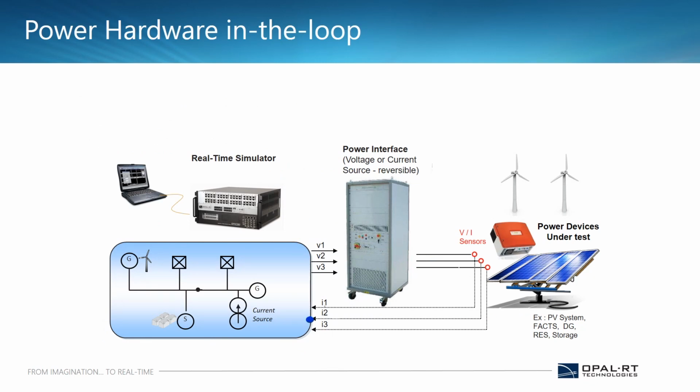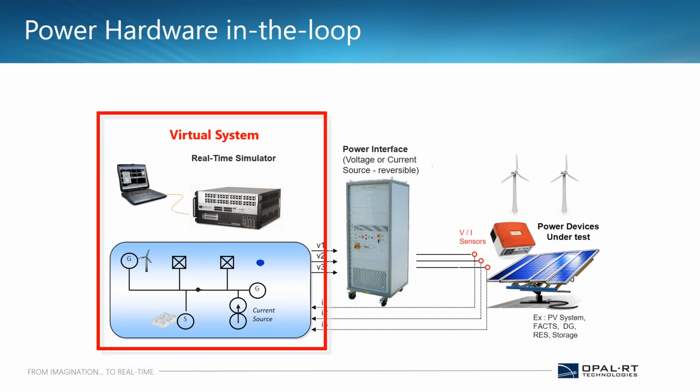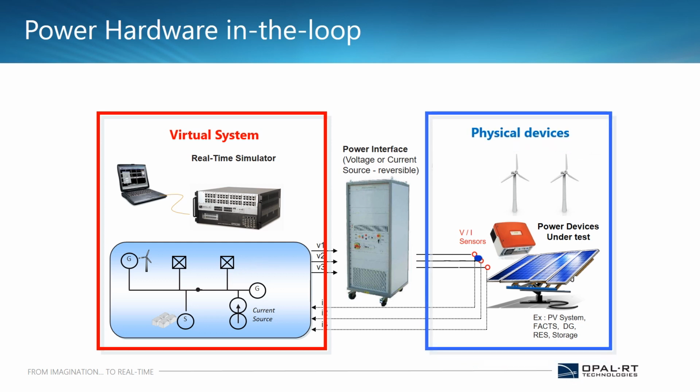So what we will do, we will take the voltage and current results from the real-time model which is running on the real-time platform. We'll send it to a relay, the hardware relay. Then the hardware relay will give a trip signal based on the voltage and current commands that it has received from the real-time simulator. Then this trip signal will go back to the MATLAB model so that the different types of breakers or isolators connected across the power system network will receive the trip signal and isolate the faulty section from the live section of the model.